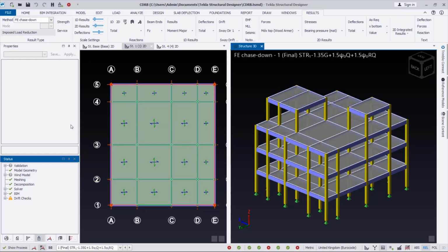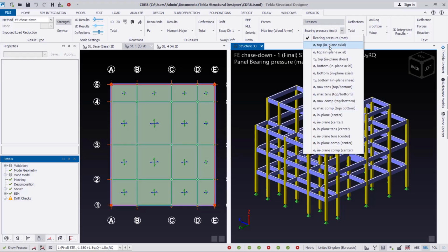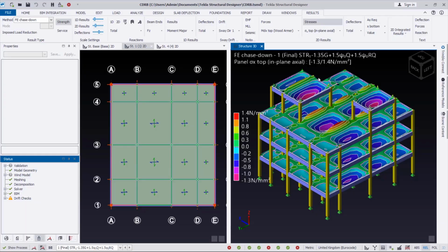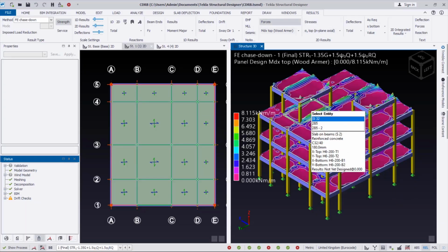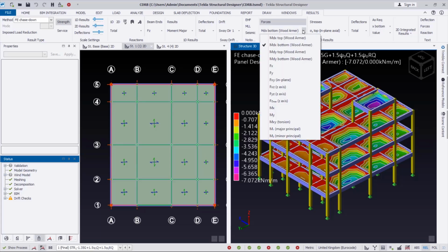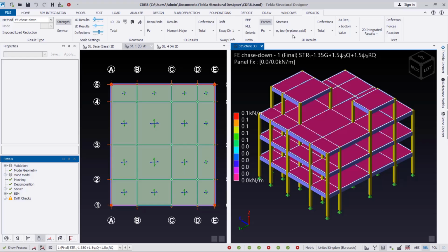So once this is active, you can come over to where you have the stress right here, activate the stress. Once you activate the stress, you can activate any of these, so you have the stresses on the slab, okay, based on the FE. All right, so you can activate the forces as well, and then be able to use the Wood and Armer method to check, okay, as to complete the analysis successfully.